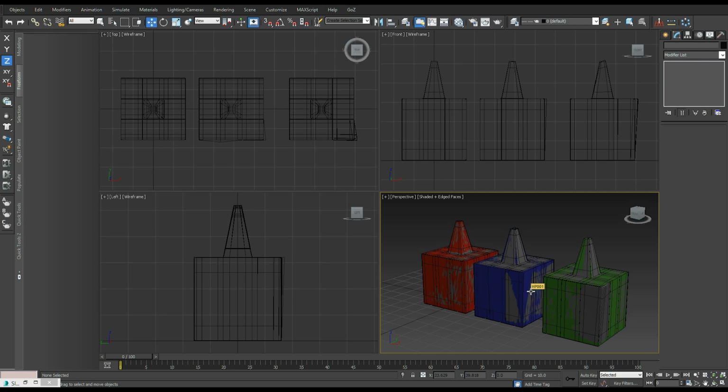So it's not going to be necessarily on how just to use the Baker in Max or just use xNormal, but an overall view of texture baking in general. I'm also, later on in the tutorial, going to be using a project I'm working on, so we're going to go a little bit beyond just looking at a couple boxes and stuff like that. But I'll show you a whole workflow from coming out of ZBrush, bringing it into Max, setting up the low poly, and doing the bakes, and then out to the final render, checking for errors, all that kind of stuff.